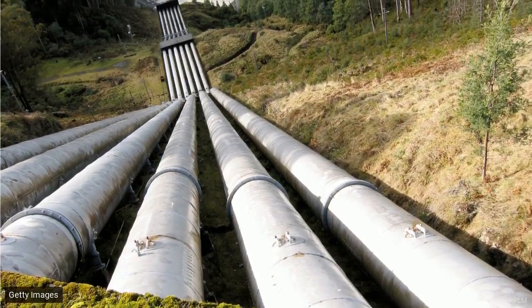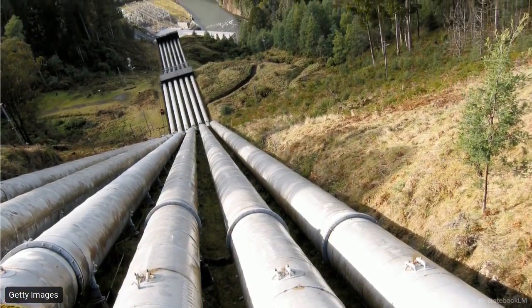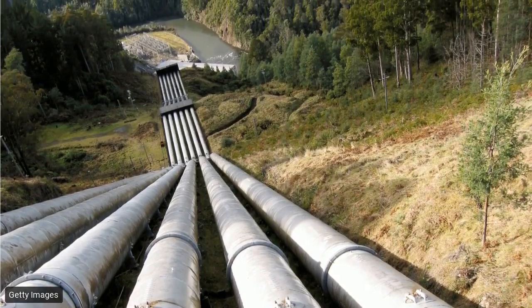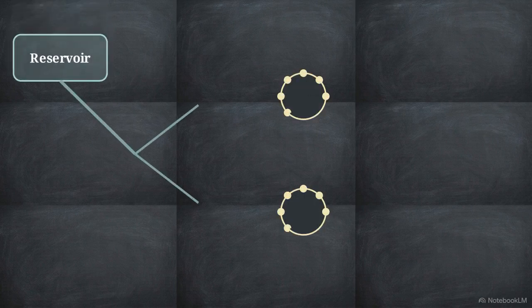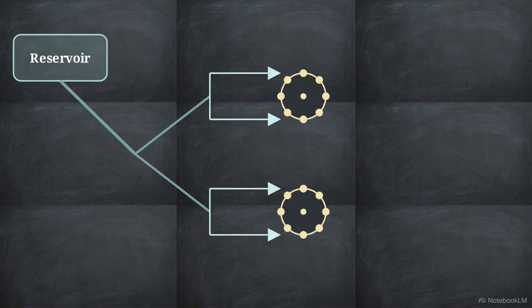Now for the most complex scenario. You have a 3-kilometer pipeline feeding 2 separate Pelton runners with 2 jets per runner. You must also account for transmission and runner efficiencies. When faced with this much data, map the physical path first. Water leaves the reservoir, travels the pipe, and splits to 2 runners, each with 2 jets. That is 4 jets total.